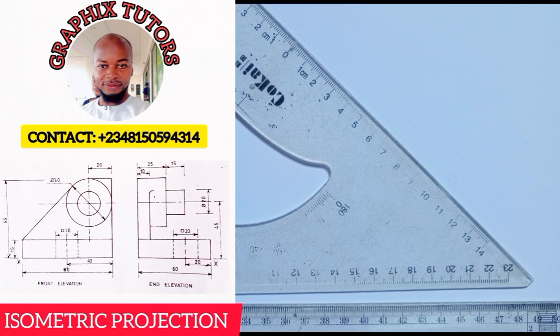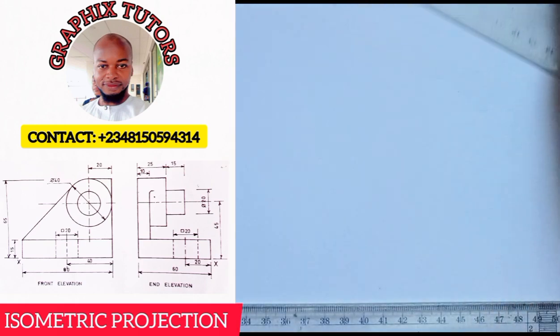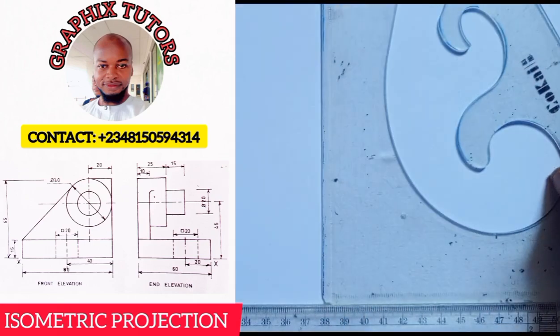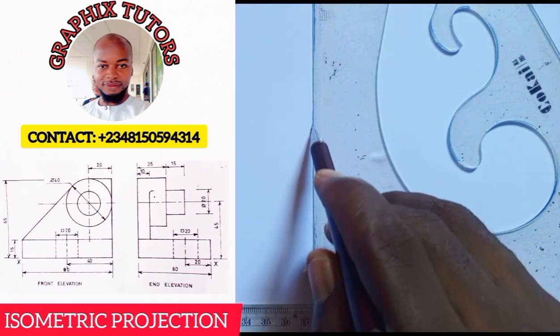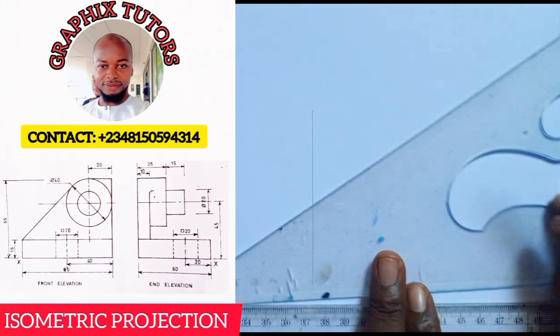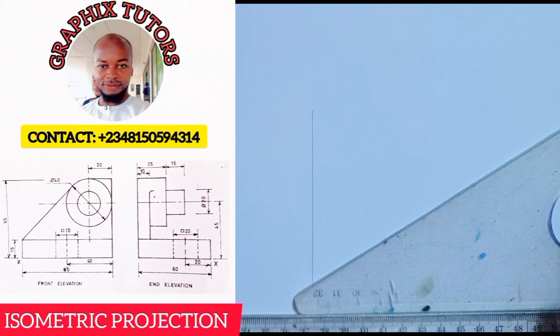So when you hear the word isometric projection, the first thing you have to do is draw your isometric axis, right? That is, you're going to take your vertical axis, which will be taken as our Y, and we're going to take the horizontal axes, which are inclined at 30 degrees on both sides.